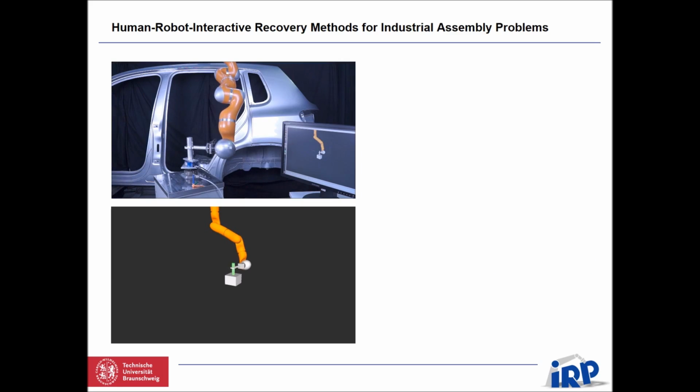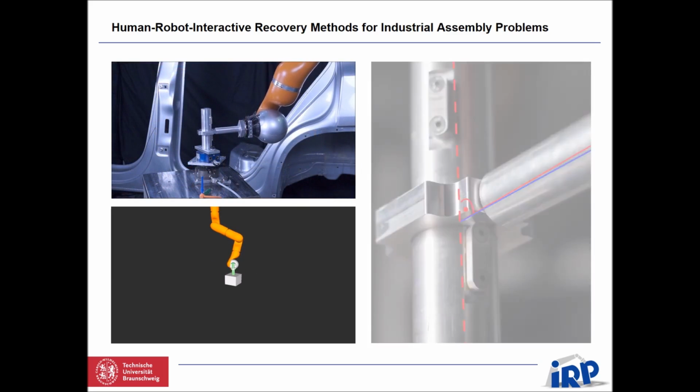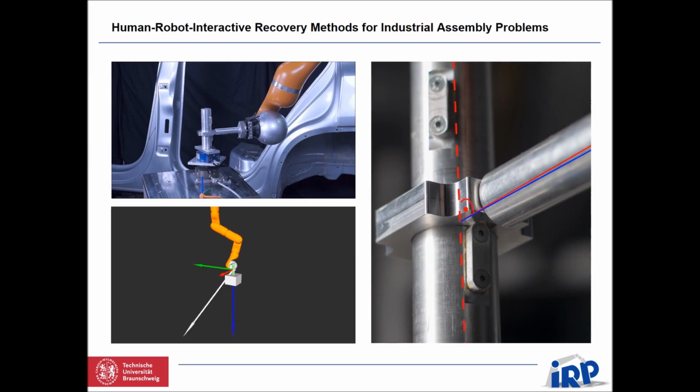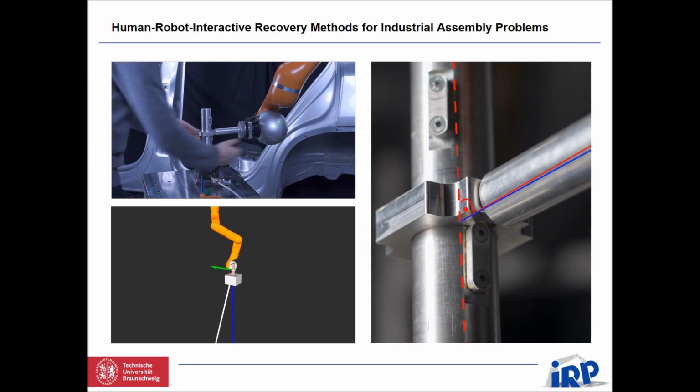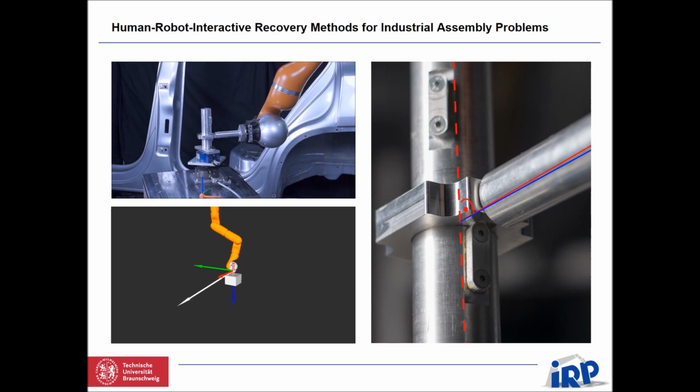Driving on, the robot will face the bottom assembly problem. It rotates too much around the shaft axis. As a result of this, the notch of the conrod will not be able to pass the shaft's key, what we can see in the picture on the right. To solve this situation, we took the kinesthetic teaching mode as an example and helped the robot getting on the shaft's bottom key.